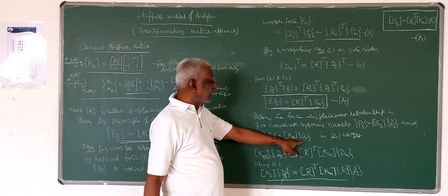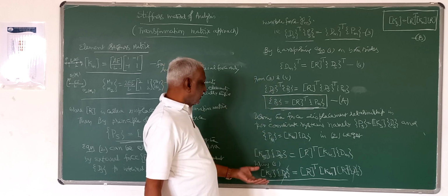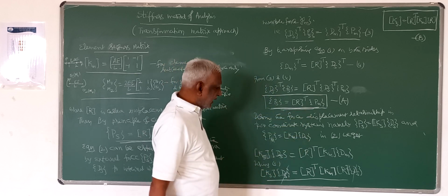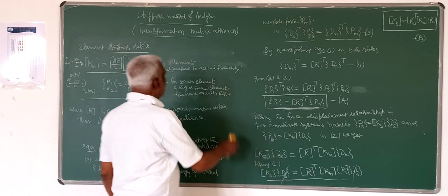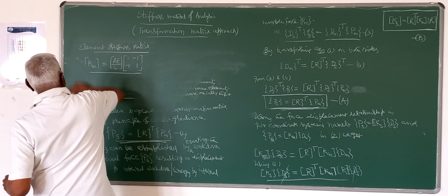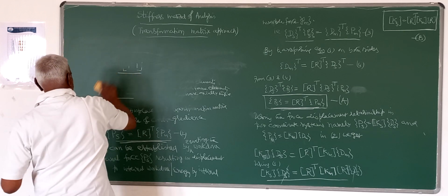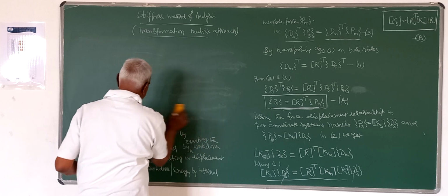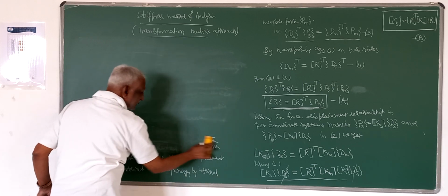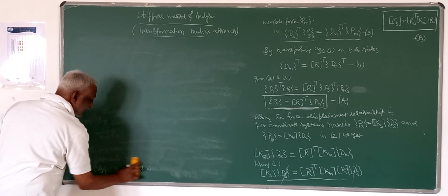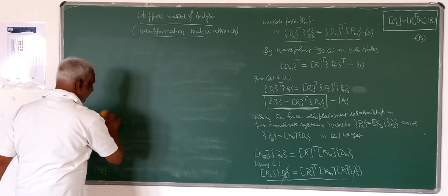Again, this displacement ds, you can convert from the global into dm from that relationship of force displacement transformation. Then you can evaluate the combined internal member forces. Thereby, you can complete the analysis, that is the internal member forces as well as the displacements you can evaluate.